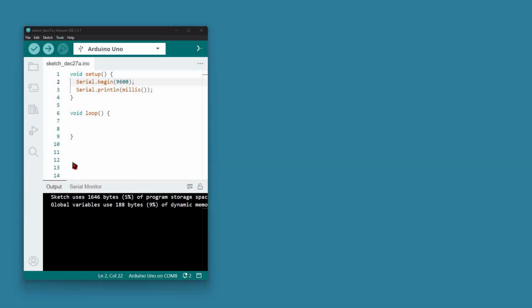There might be situations where you need to use the millis function in the setup block. For instance, we might want to measure the duration or performance of commands executed at the beginning of the program. During the delay intervals generated with the delay command, millis continues its counting process. For instance, let's introduce a delay of 2000 milliseconds here, and then let our millis function run.